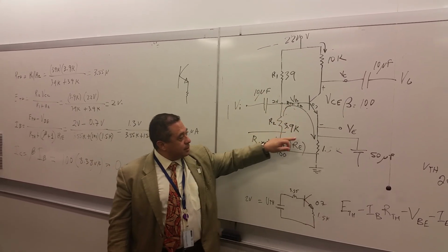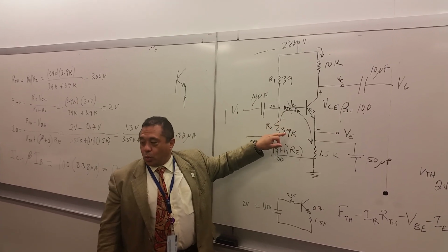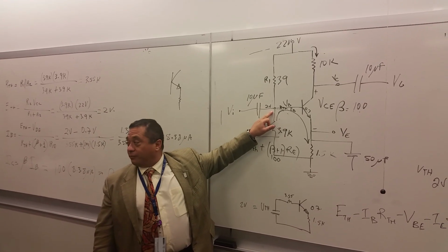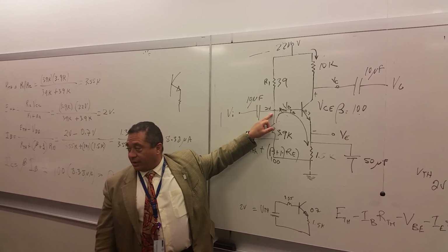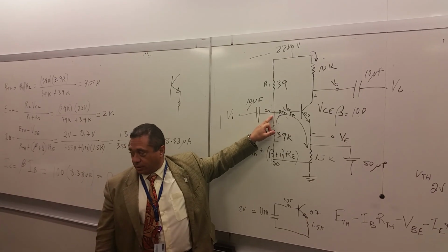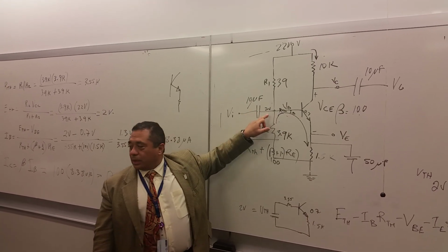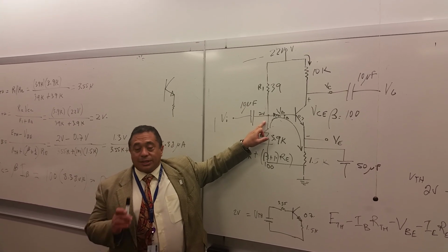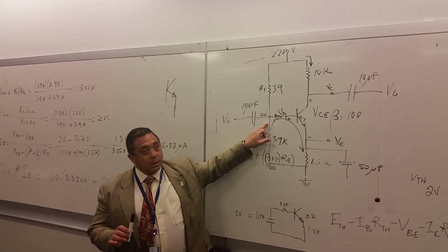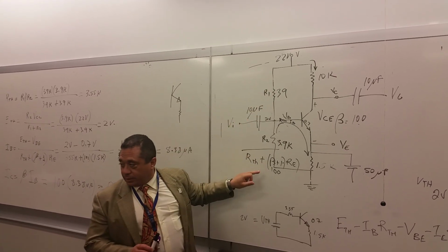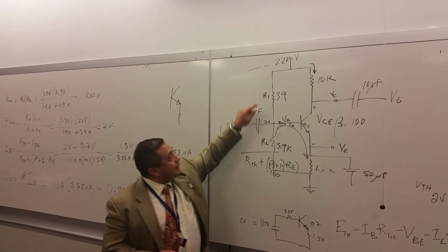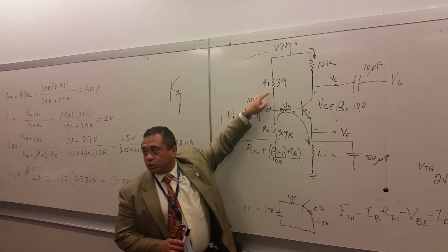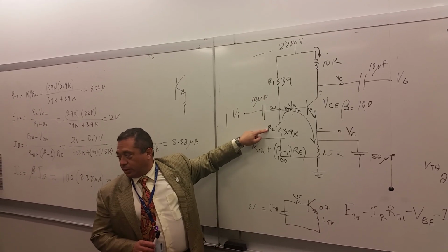do the analysis of this loop, we need to first calculate the Thevenin equivalent voltage and resistance. Thevenin voltage and Thevenin resistance, correct? Now, how do you calculate the Thevenin resistance? You start by shorting out the power supply, and when you do so, this point is the same as this one. So these two resistors are in parallel, right?